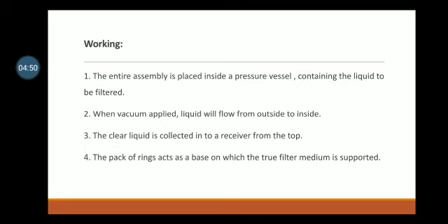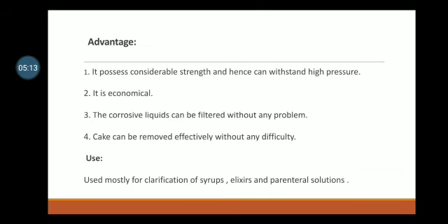Working: the entire assembly is placed inside a pressure vessel containing the liquid to be filtered. When vacuum is applied, liquid will flow from outside to inside. The clear liquid is collected into a receiver from the top. The back coverings act as a base on which the true filter medium is supported.